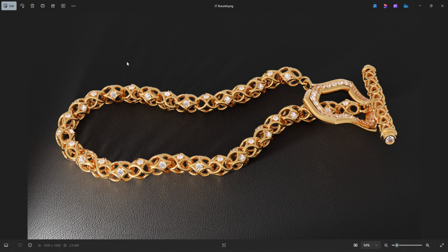Number one, physical lights like a spotlight or a rectangular light, when you have a bump map like this leather, really bring out the bump map, so you get a very defined surface. And then you can see that I took the radius down to where the shadows were soft, and so it made these dramatic shadows coming off here that were soft.